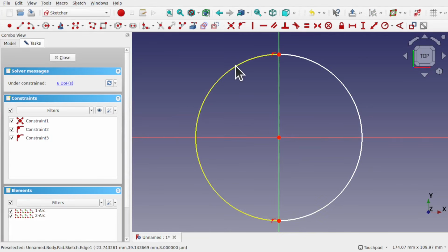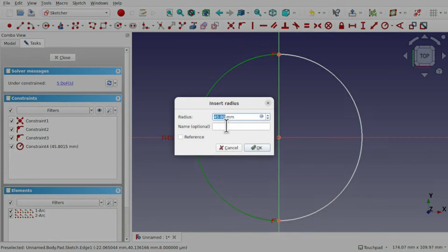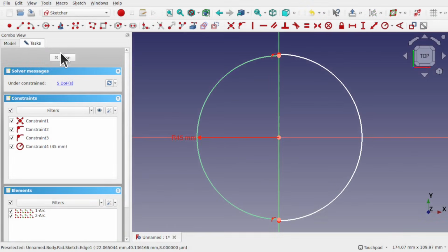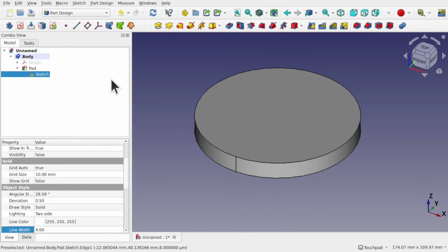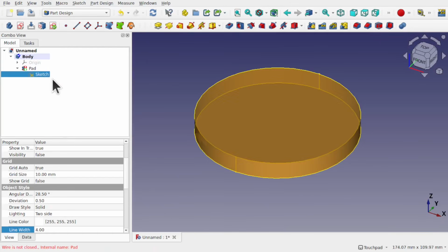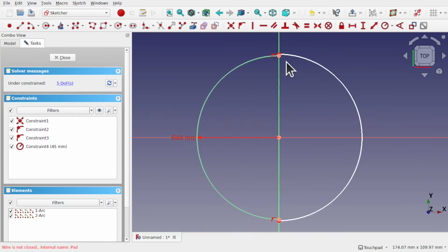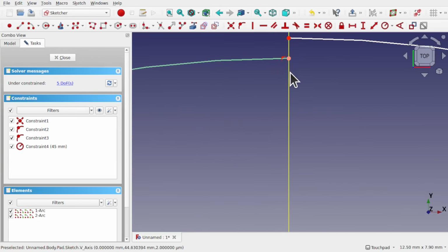Control Z that. So if I came in here and reduce this down and say, oh, I've got 45.80 here, I'm just going to take the 80 off and hit enter, hit close, and then straight away we got a problem. Why not closed? Because we just rounded that down, but as you can see, this has moved away from this point here.